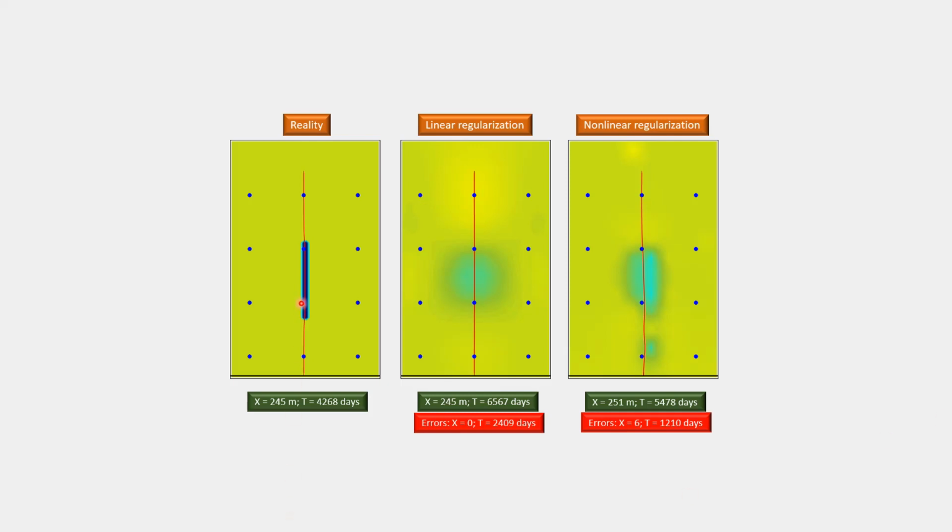So here's reality. Here's what I got before. And yes, what emerges from the calibration process does better reflect the source of the signal that appears in those 12 wells. Pilot points, of course, cannot represent a feature like this, but because I have many pilot points, they don't do a bad job of representing the elongate nature of that feature.